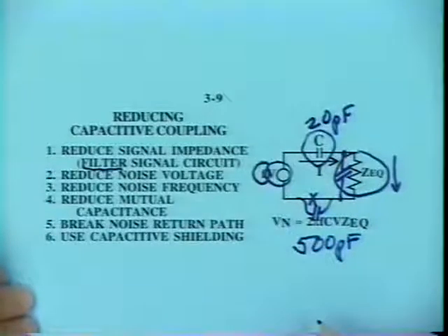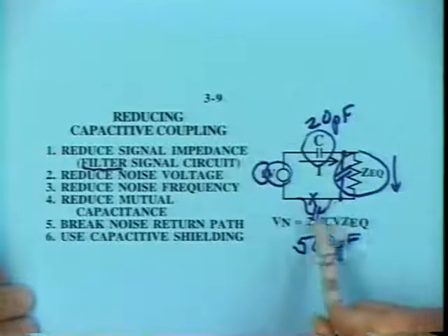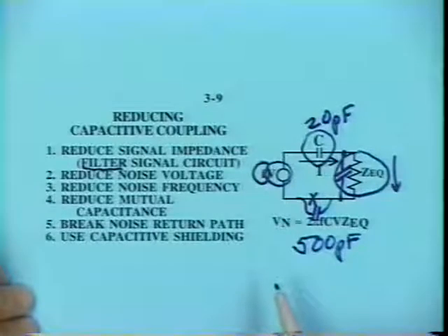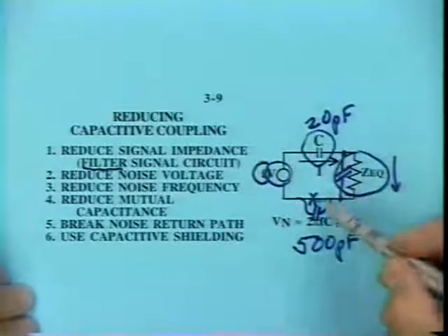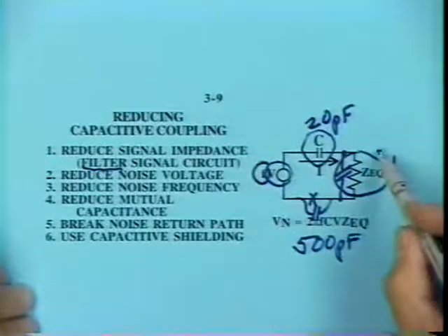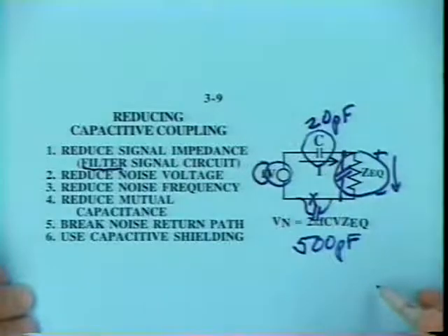We're thinking that we're dramatically raising the impedance by disconnecting that wiring, and actually we're not doing that. We're making very little change. So we get about the same amount of current continuing to circulate, and about the same amount of voltage across the equivalent circuit, even by opening up that path.